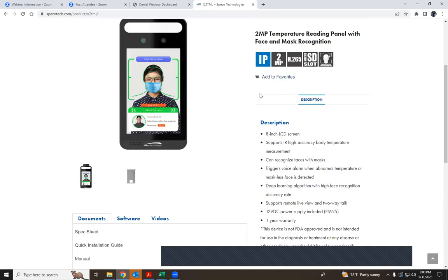It does have a Wiegand input and a Wiegand output on it. It has a door lock module built into it, and it utilizes 2 alarm outputs. So just like we were showing you how to trigger different things based off of a successful event, we can utilize facial recognition built into our facial recognition cameras. And this one also has facial recognition built in.